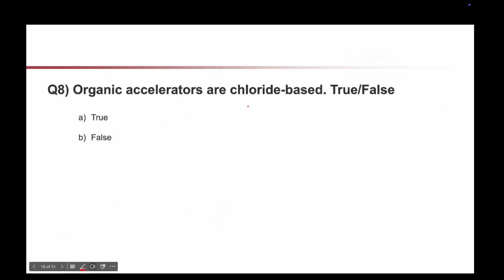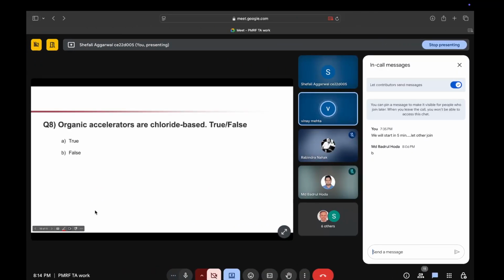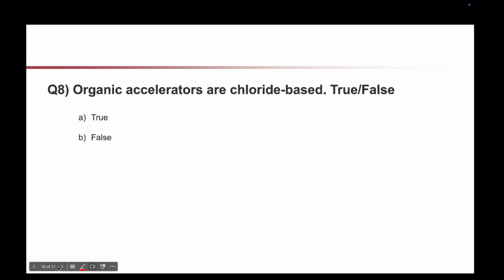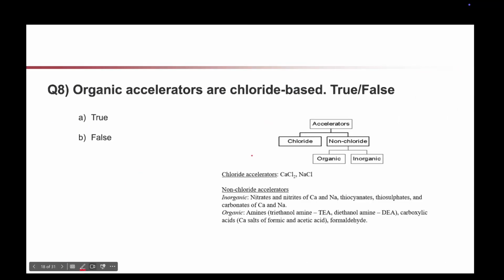Next is, organic accelerators are chloride based. True or false? True. Okay, I will give you that graph. Mainly we have chloride and non-chloride based accelerators, and organic accelerators come under the non-chloride accelerators. So it is false. Yeah, correct.